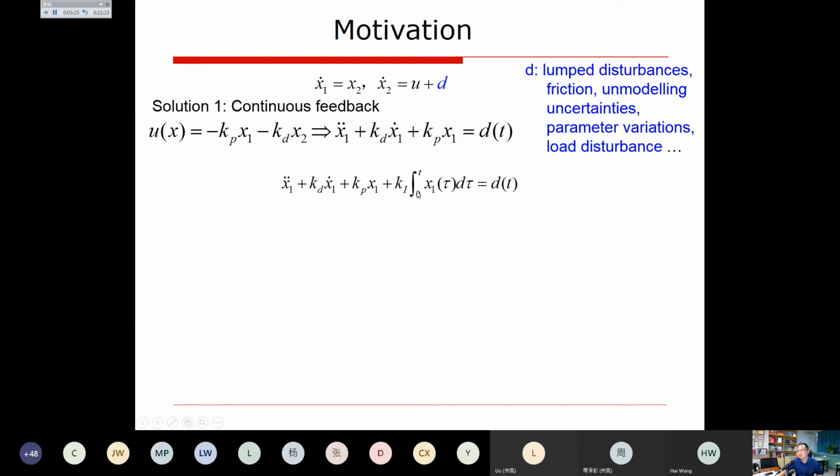So in another way, if the disturbance does not converge to a constant, then you cannot use integral to get a good enough tracking effect. Then the position error will be a bounded error. It depends on the gains, Kp, Kd, and Ki. But usually you cannot adjust the gains to be high enough because of the control saturation, because of the stability conditions, right? So in this case, the performance will be limited. You cannot enhance it if you just use an integral action for disturbance.